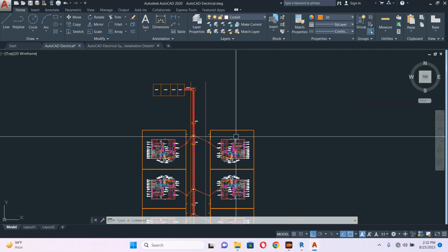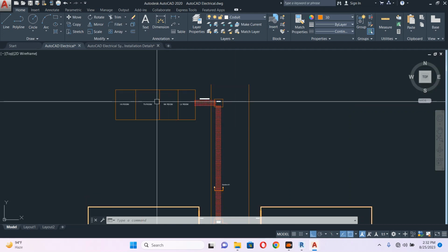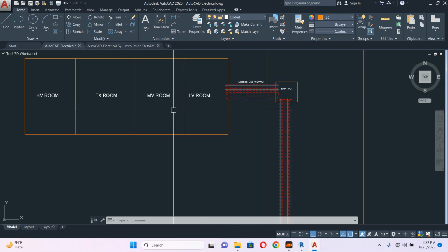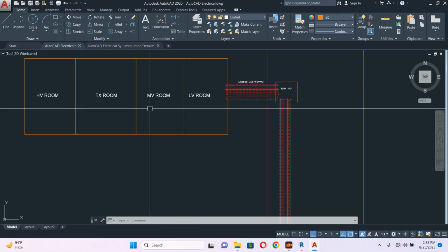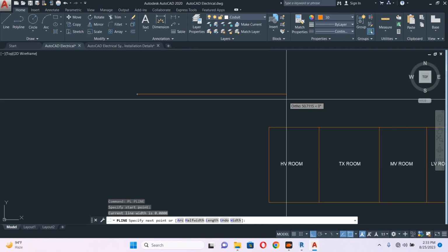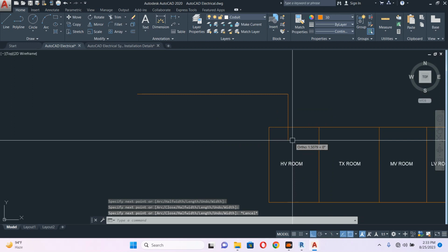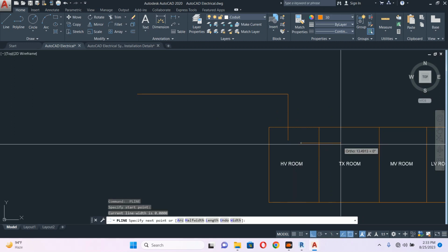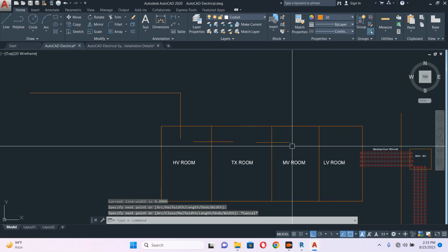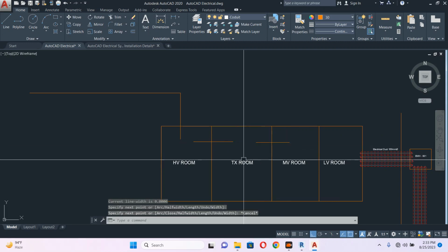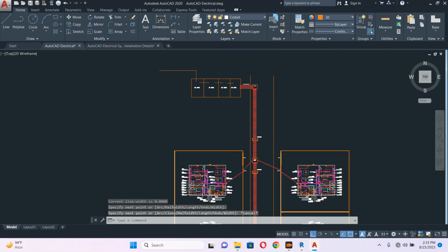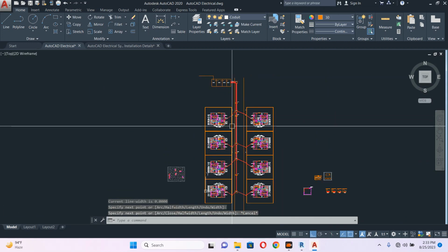Sometimes this one is with the government, sometimes this one can be private. If you see a big building, they will be private here. So what happened? Government will bring cable from here to here, something like this. From here to here it will go to transformer, from transformer to MV. Why transformer? I will tell you. From MV to LV, from LV to these DBs.